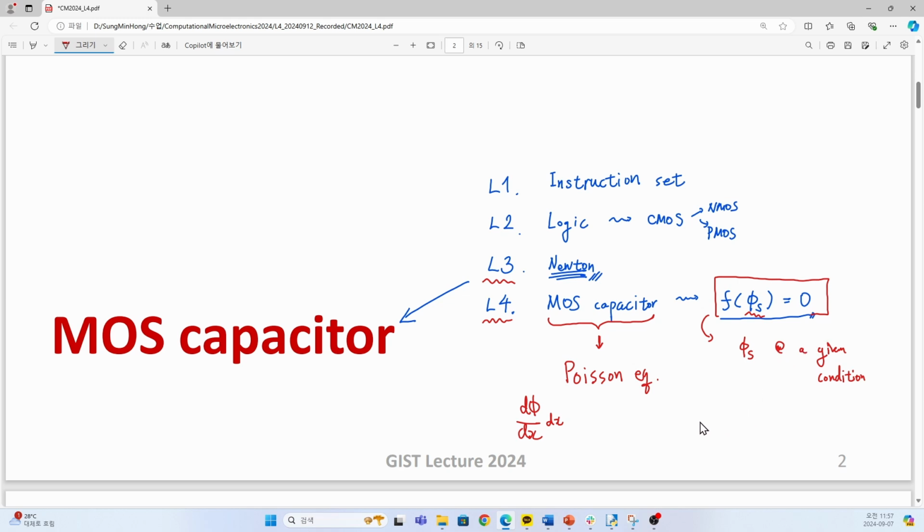So now it means that if we know the surface potential gradient, we can calculate the surface potential. This is a huge improvement from the viewpoint of our application to the MOS capacitor, and the next time by using that information we will get the voltage characteristics of MOS capacitor.